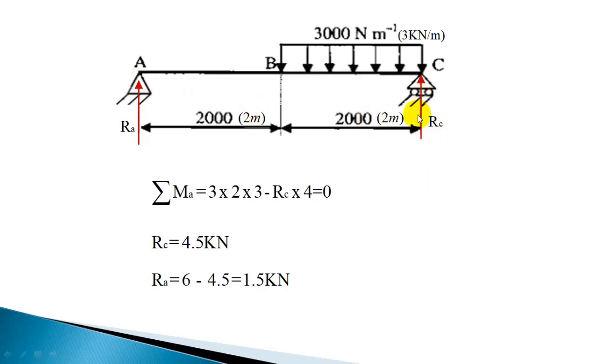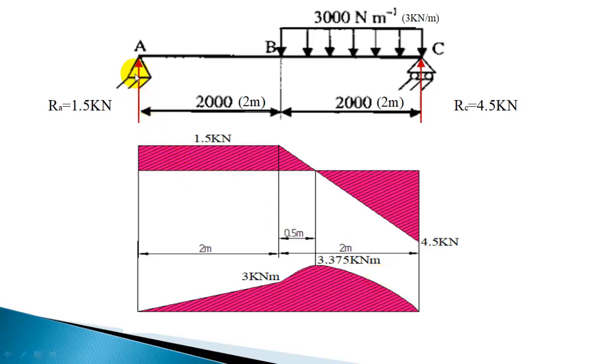After getting the reactions, we can find the shear force and bending moment. So 1.5 is the reaction here. So in this section the shear force is 1.5 kilonewton.